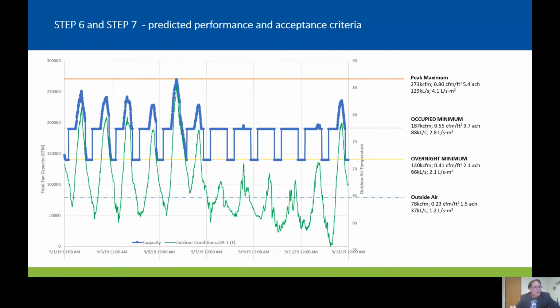It's a little bit harder than it sounds. First off, make sure that you can measure CFM, or fan kW if you can't measure CFM. If you miss that in design, you're screwed. But pretty literally, once the system is up and running, you let it run in automatic for at least 5 days, and you confirm that the system is turning down according to the design intent. In particular, you want to confirm that overnight turndown and make sure that your systems are actually ramping down to what they were supposed to do during design.